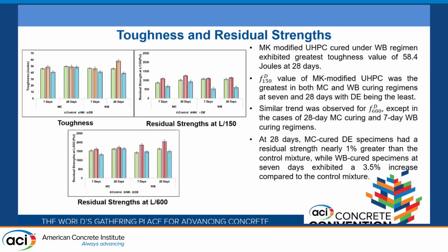and the MK mixture also showed better results for the residual strength at L/150, whereas the DE had the least residual strength. A similar trend was also observed in residual strength at L/600, except in the case of 28 days MC curing and 7 days WB curing.